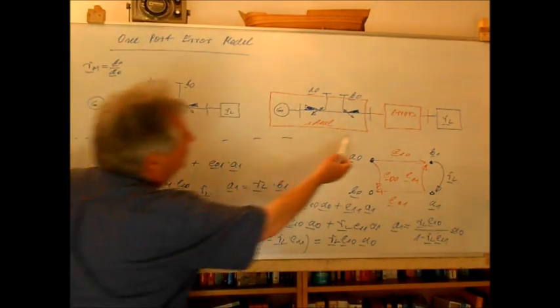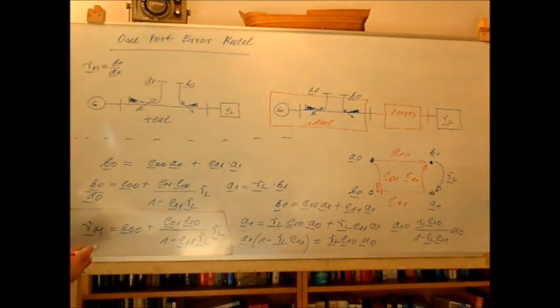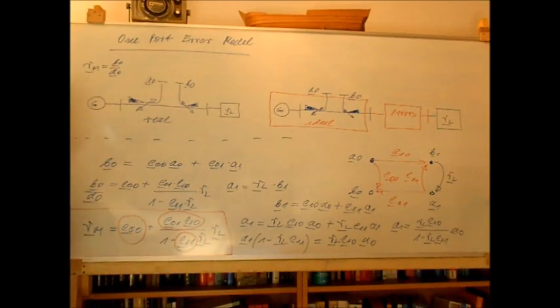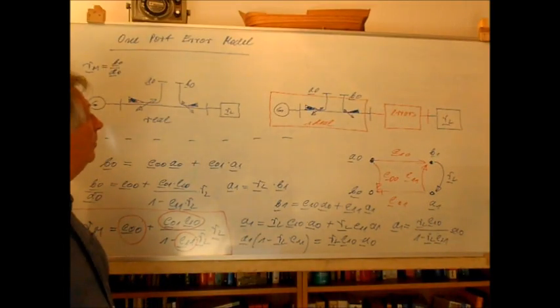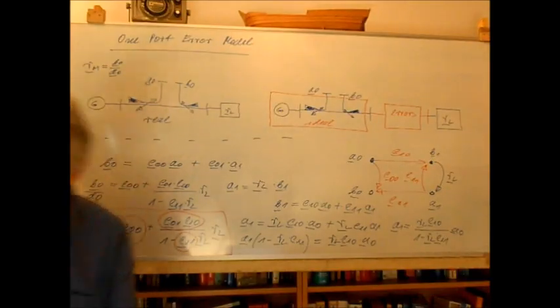then we introduce all the errors in a two-port here, and this will result in 3 different error parameters. This means to do the correction for the 3 error parameters, we need 3 calibration standards, and this we will discuss in the next step.